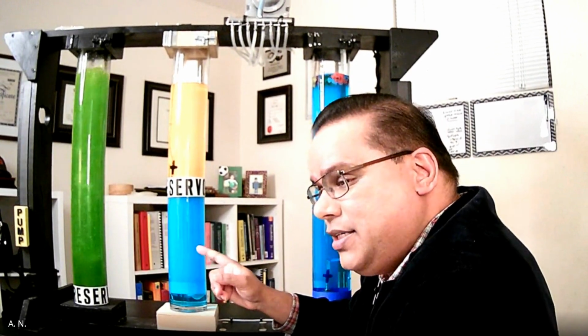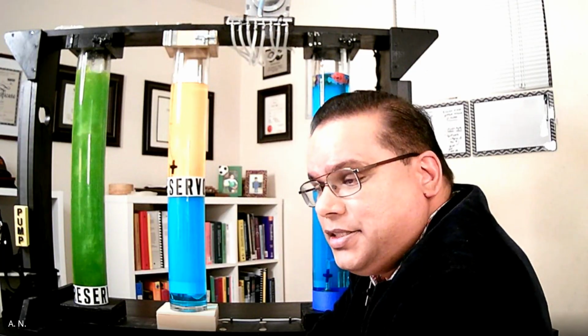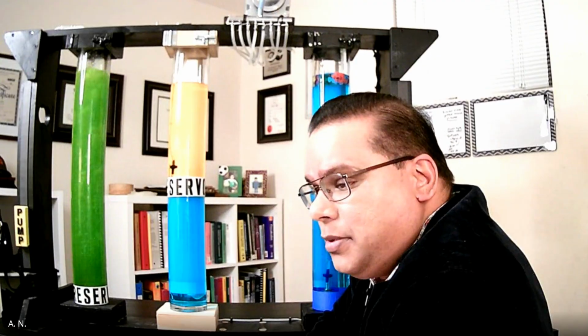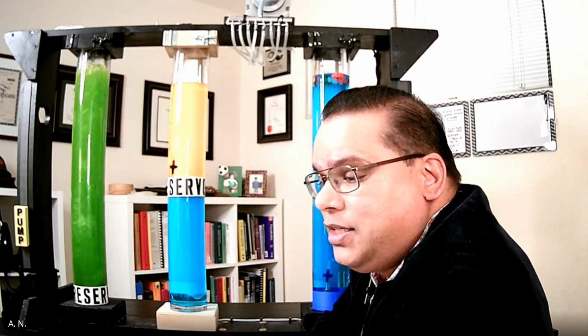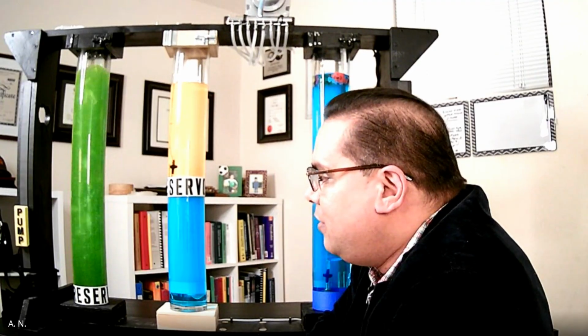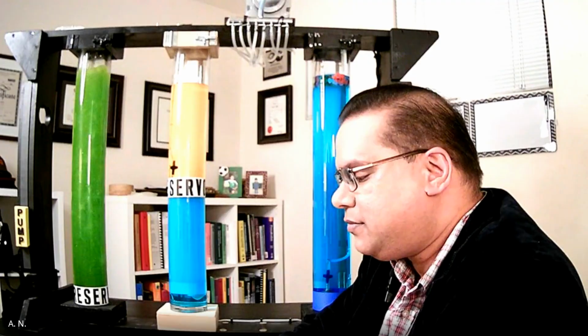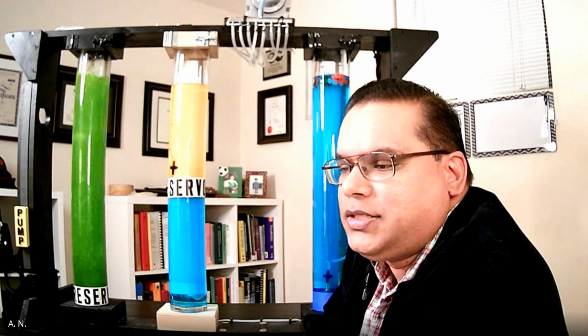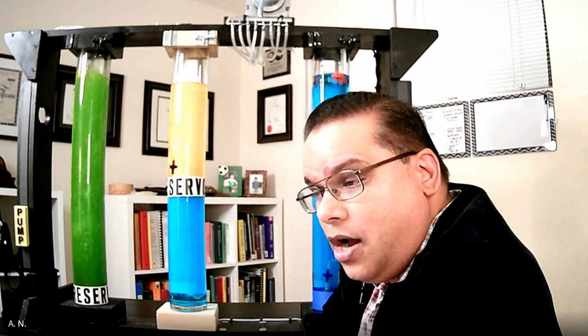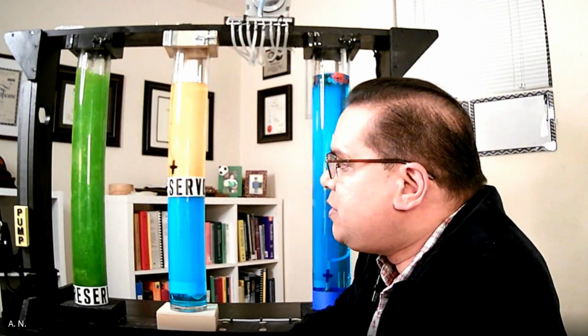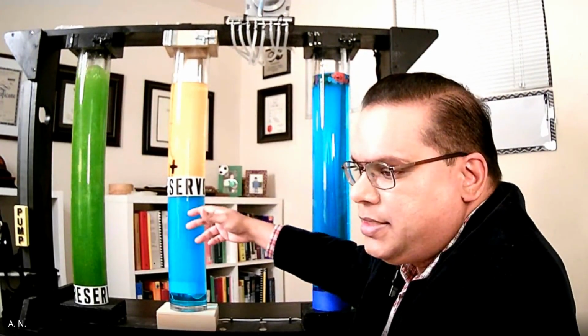This here is the very reason why you have high fluid levels in your wells, and why you can't operate them: you're not making the right calculations. You're only using an oil column above the pump, when clearly there's not an oil column above the pump, because you are telling the water where to go. And that's not how multiphase flow behaves, right? The nature of multiphase flow is for fluids to slip and to mix. We know that behavior now, but in the past it was much simpler to analyze things like this versus this.